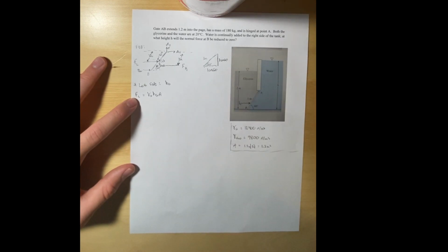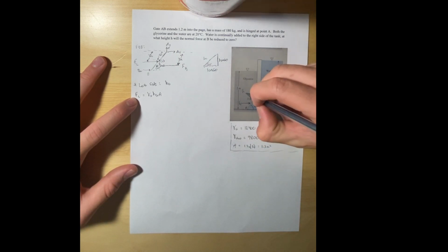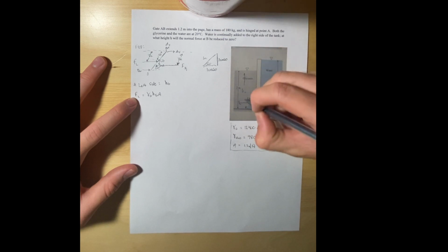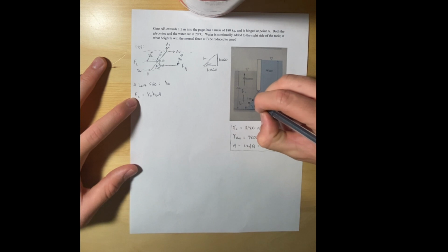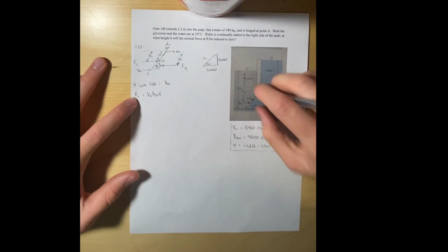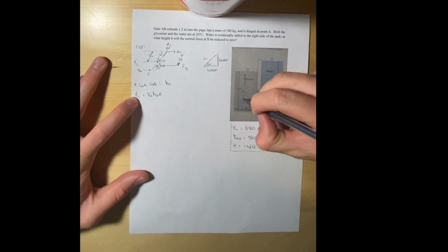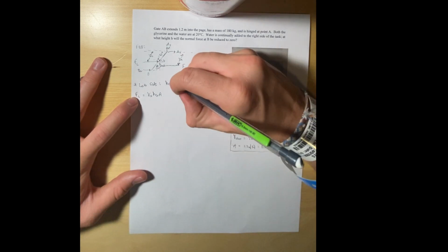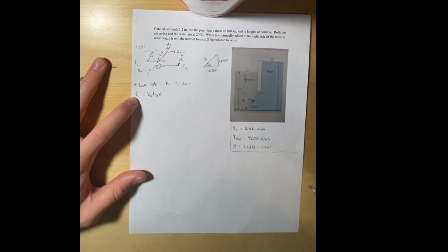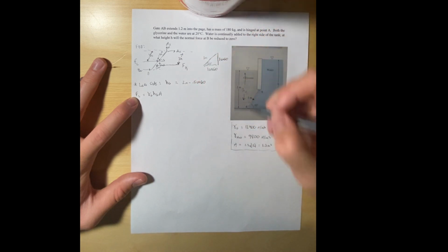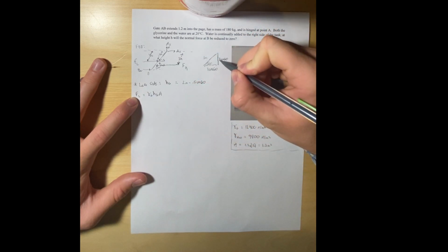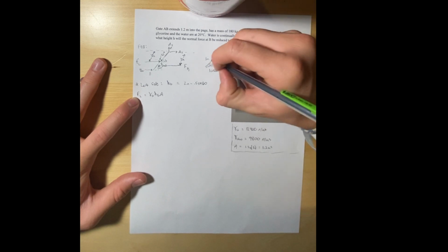So left side, calculate the force L, force of the left side. So in order to find this distance, we're gonna call this distance h sub g. This is gonna be our 2 meters. Actually, this is the distance to the center of gravity. I guess you could call it h sub cg. Just to the center right here is gonna be our 2 meters minus our 0.5 sine 60 we got from above. And we used 0.5 here instead of the 1 because we were taking it at the center, which we can assume is 0.5.